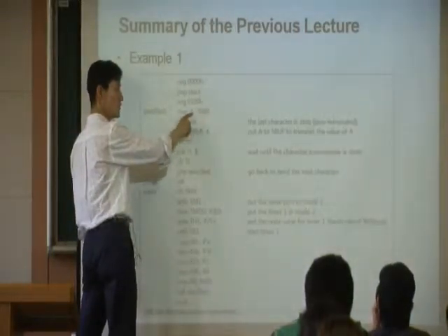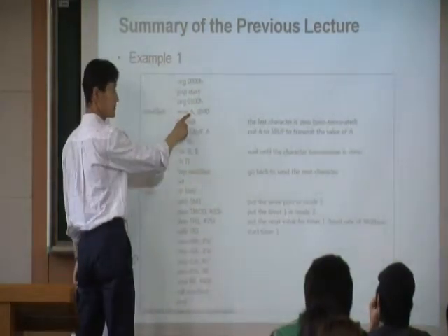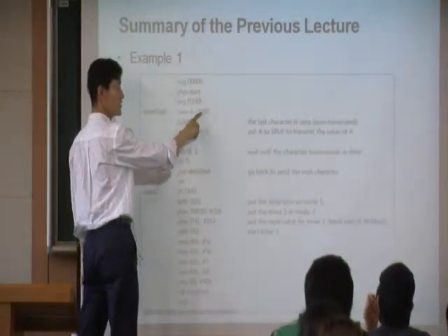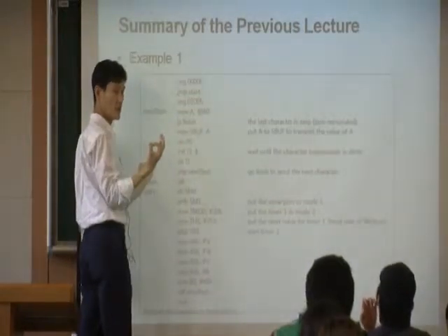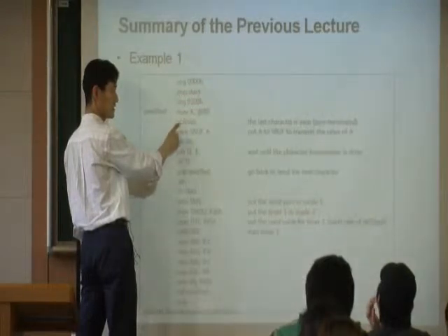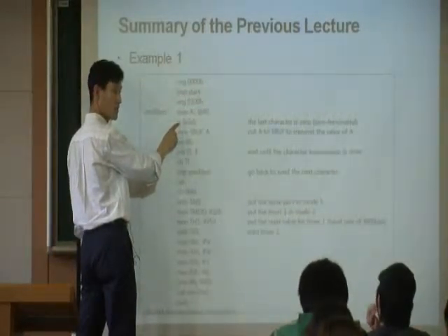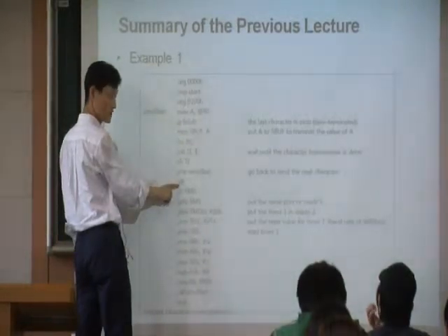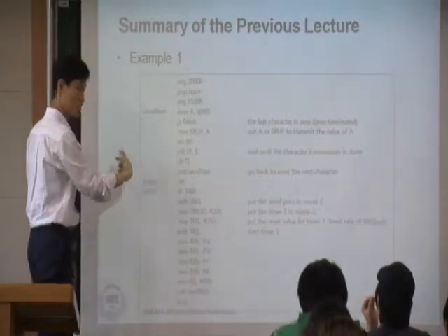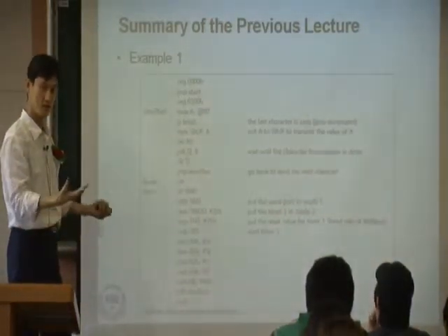And you read the 43. And actually, at 43, we have a value 0. So when R0 was 43, the accumulator has the value 0. Then on the next line here, we actually have a condition. The accumulator is 0, so we need to jump to finish. Finish is right here. Return. So therefore, you are going to return. We return to here, end. So the program is ended.